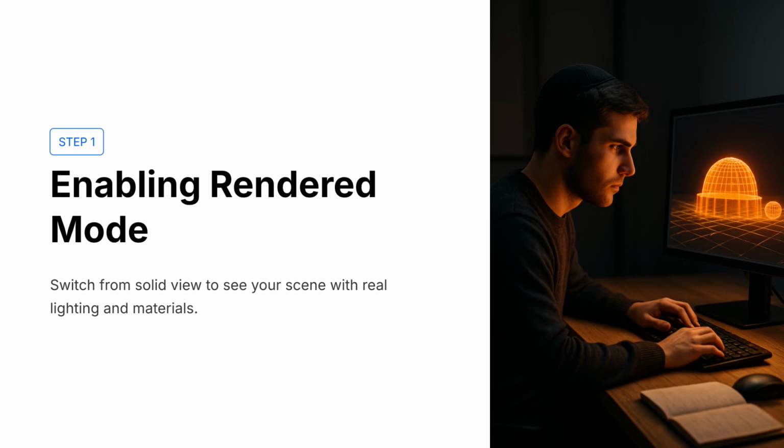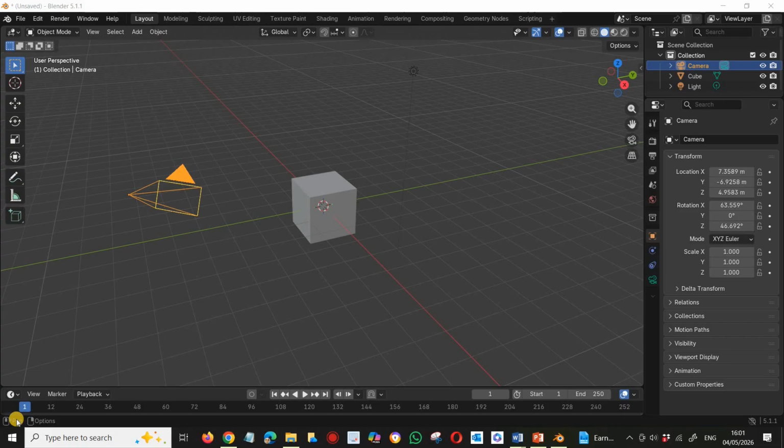Step 1. Enabling the rendered mode. First, we need to make sure we can see our lighting correctly. Look at the top right hand corner of your screen. You'll see a row of 4 small circles. These are called the viewport shading panel. Click on the rightmost circle, the one that looks like a solid rendered ball. This enables rendered mode, which allows you to see the effect of the lights in your scene.